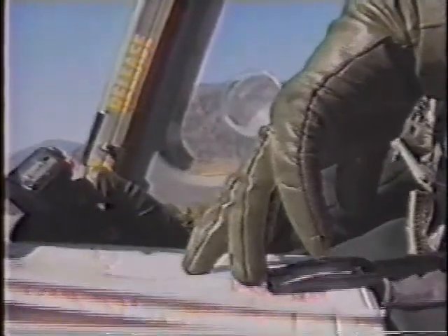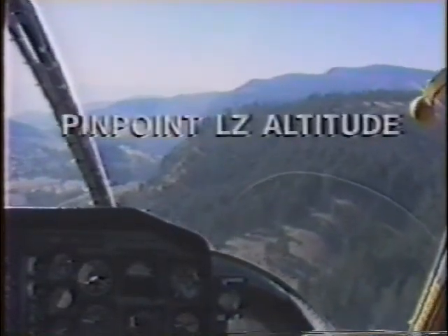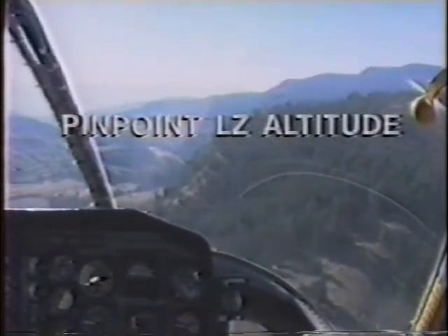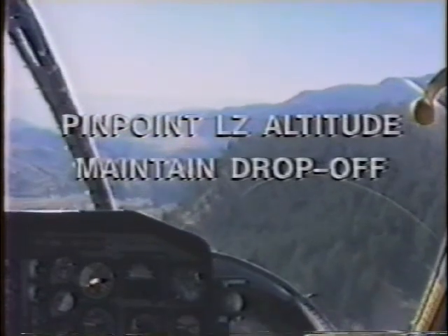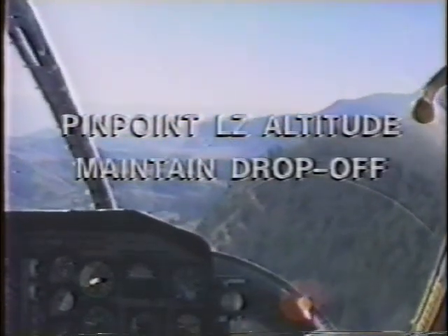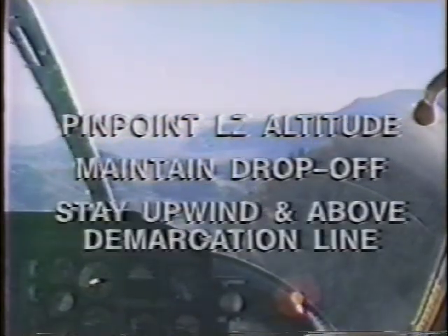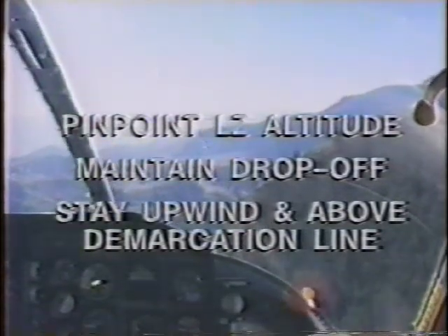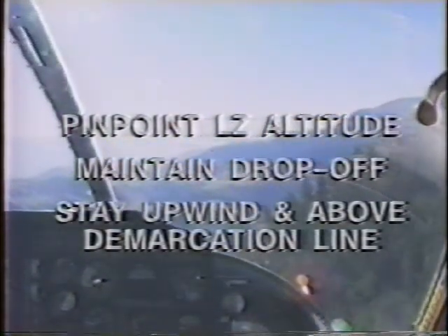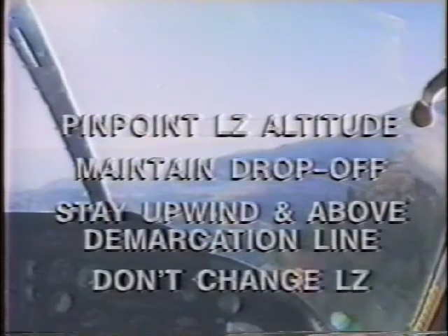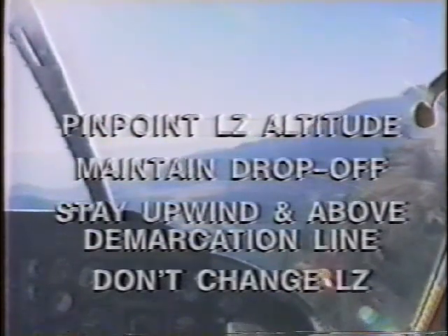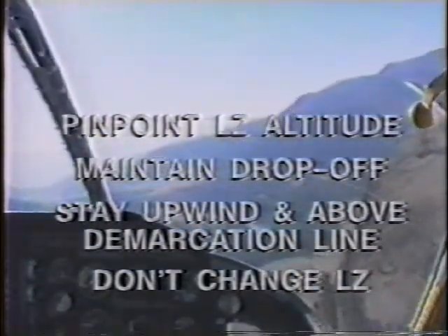Next, once you're flying, it's essential to pinpoint the exact altitude of the LZ you're considering. Maintain a drop-off escape route until the last possible moment. Stay toward the upwind end of the terrain feature and so above the demarcation line. And having made an LZ selection, don't change it unless you completely abort and overshoot.